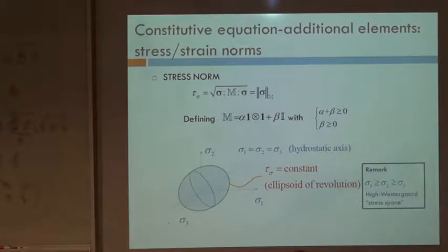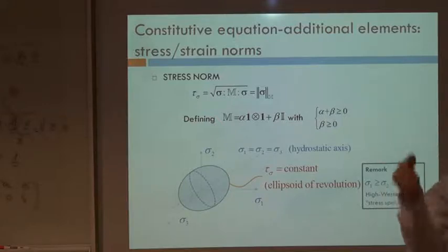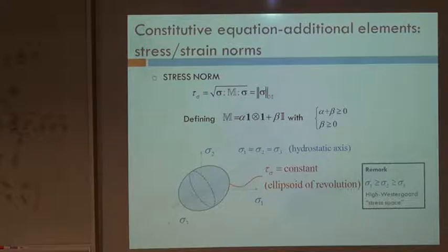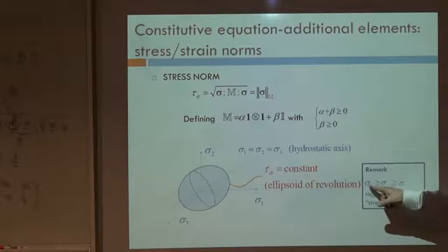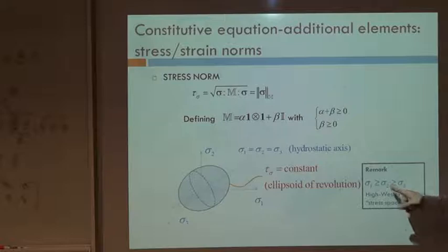So, any stress state that we have in a solid, if I just take a solid and produce some strains and I have some stresses, I take one point of this solid and the stresses that this point has at this time. From this, I can compute the principal stresses, which is computed using a diagonalization process, an eigenvector problem. So I take the 3 eigenvalues, which are called the 3 principal stresses, and I order them: sigma 1 is the larger, sigma 3 is the smaller, sigma 2 is the intermediate.